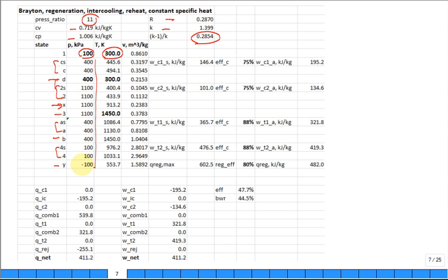You don't put those in right away. And then it's bouncing up and down to get those temperatures. Just like I showed you, the equations to apply the temperatures. And this temperature was fixed coming in, so it's like you solve down to, you can't solve for X right away. And then you solve down and you can finally solve for state 4. Knowing the temperature at 4, then I can finally solve for X and Y.